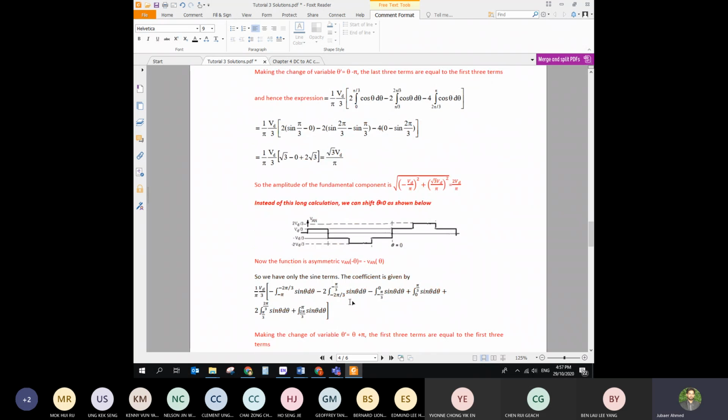So now look at it. This is the same signal as before. So this was the 0 point. Now instead of that, if we consider our 0 point is here, then we can say that this is a symmetrical signal on the right side and the left side. In that case, we do not have to consider that there is a cosine component involved, since it's a nicely repeating signal based on the 0 point. Then we just have to consider there is a sine component, no more cosine component. But since our 0 point is here, our upper limit and lower limit are going to be a bit different.